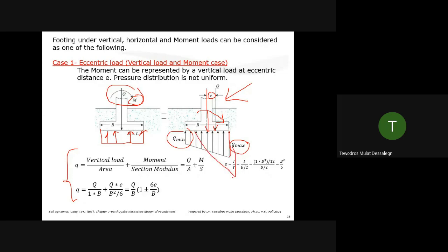So what you studied in the eccentric loading applies here, because seismic causes eccentric loading. When you see the building shaking like this, it's causing eccentric loading, so you can design it properly like that. This is a pseudo-static approach. You use a single, conservative acceleration, convert it into a force, and then get your moment, and then get your eccentricity, then follow the static case.